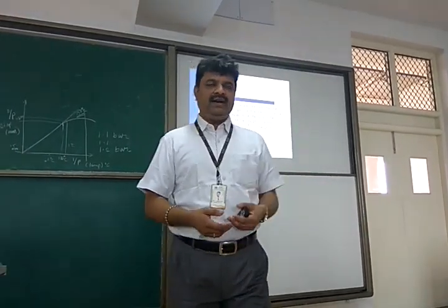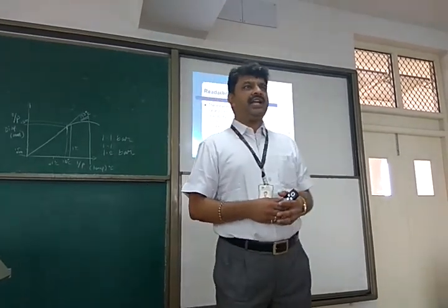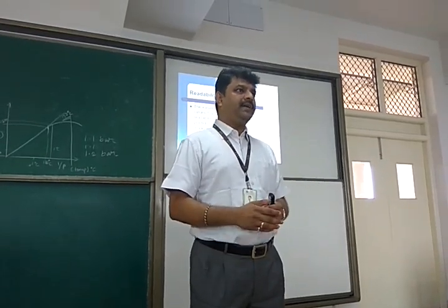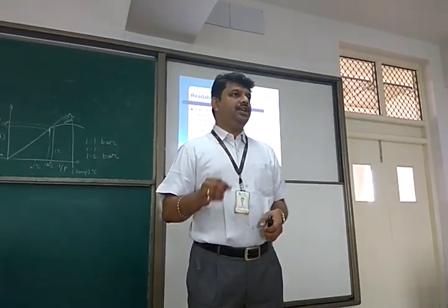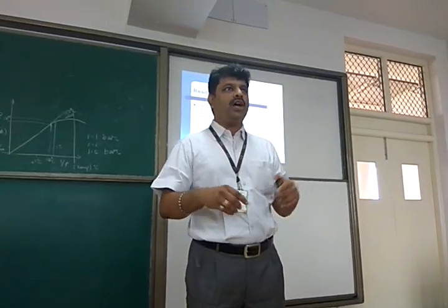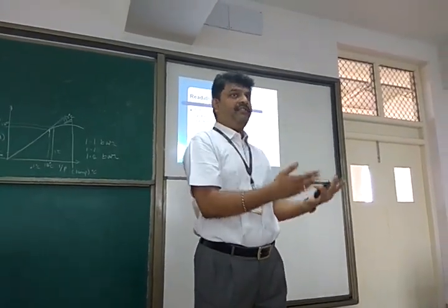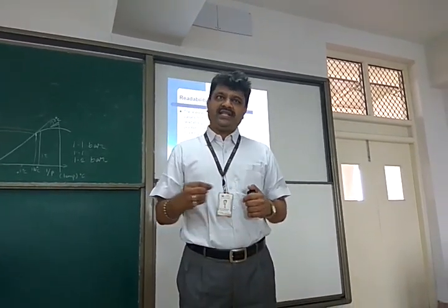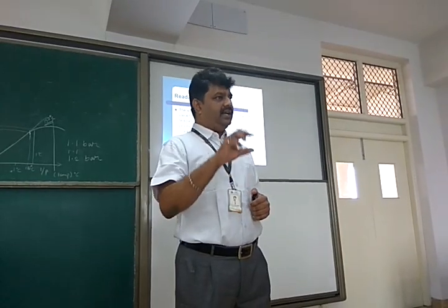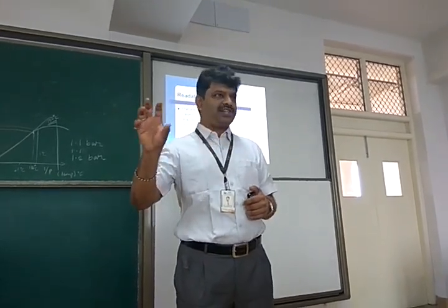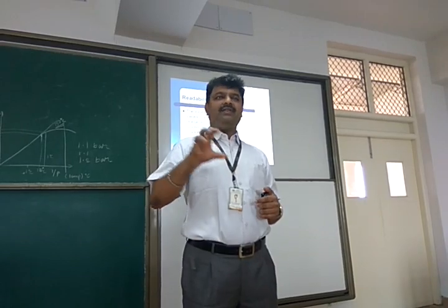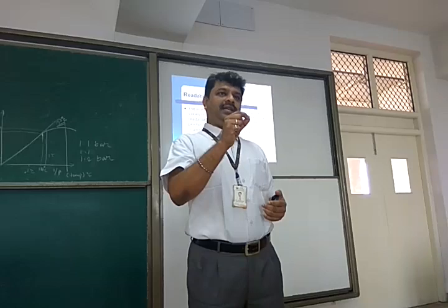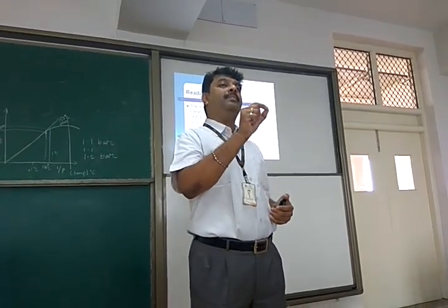Why do we learn readability? Because there are industrial regulations, especially for analog meters. In an industrial atmosphere, if a person's duty is to watch a gauge quite often, his eyes will be strained very much. So there is an industrial regulation. If a meter is to qualify as an industrial gauge, and it will be used in a shift where people often take readings in an 8-hour shift, then the instrument should have 1.5 mm per graduation.